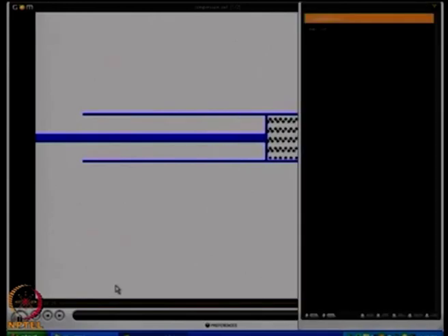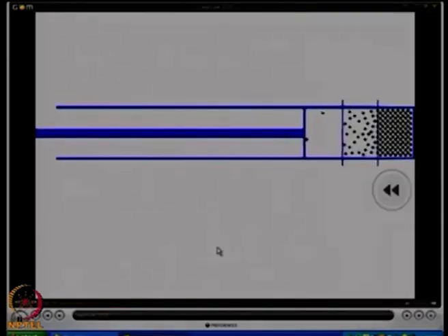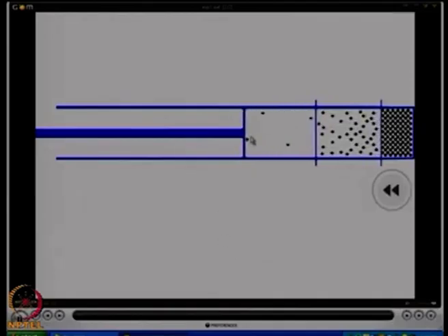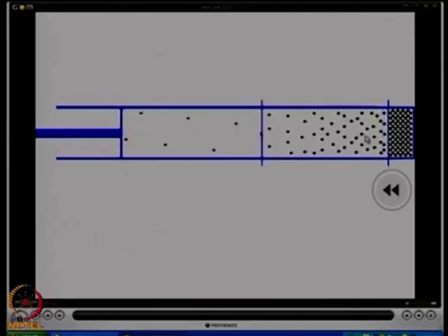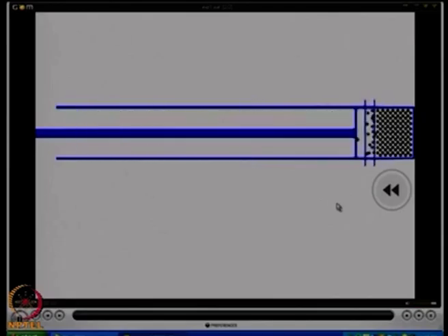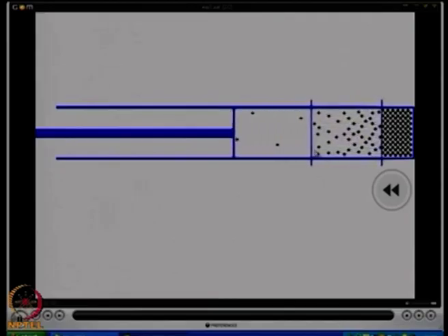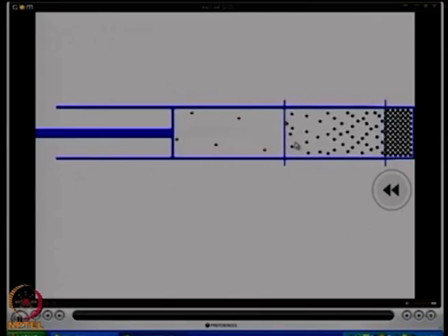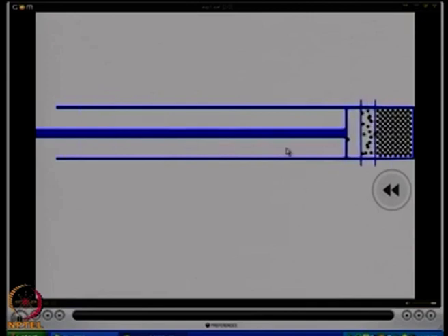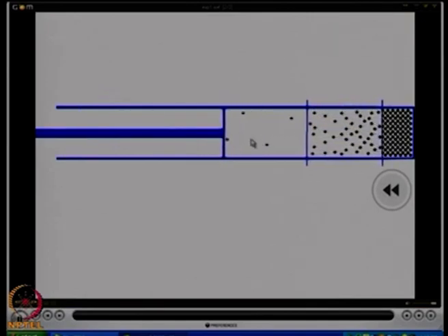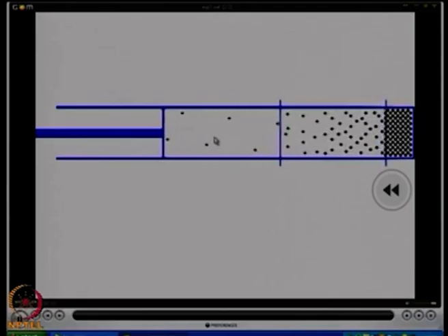Now we will look at another animation where this is the opposite. If the piston goes the other way, then the high pressure gas is now expanded to a low pressure gas, and it is expanded in a slow gradient, slowly. So there is a big set of expansion fans sitting in this whole region. There are so many expansion waves inside here. The density is slowly decreasing from here to here, and then after the last wave, the density remains constant. That happens in an expansion wave. These things we already knew.